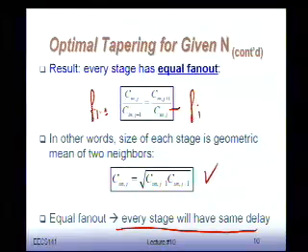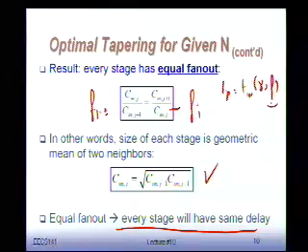And that's true, right? If the fan-out factor f is constant, remember, Tp, the propagation delay of the stage, is going to be equal to gamma plus f. So gamma is a technology parameter. You have your T invert here, which is another technology parameter. If I make f the same for every stage, every stage will have exactly the same propagation delay, right? So what does that now mean?